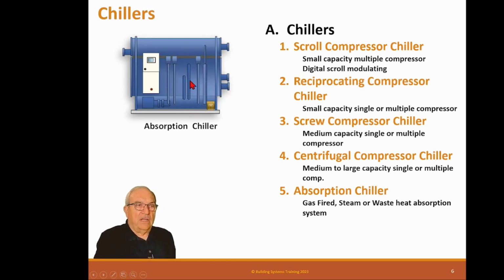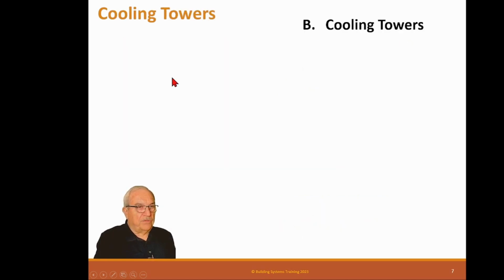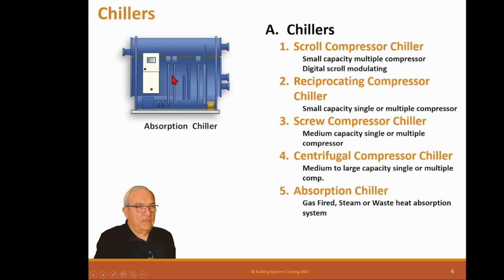So not a lot of people are trained to operate on these, and the only problem we ever had with these is if you let your condenser water get away from you, you can actually freeze up the refrigerant inside these things. The refrigerant inside these things will actually solidify. We call it freezing up. They're not actually frozen, but because their chemistry is not like water, they will actually turn into a solid. To fix it, you have to have a service guy come in and heat this stuff up high enough to melt it back again. And once it's liquid again, then you can continue the operation.